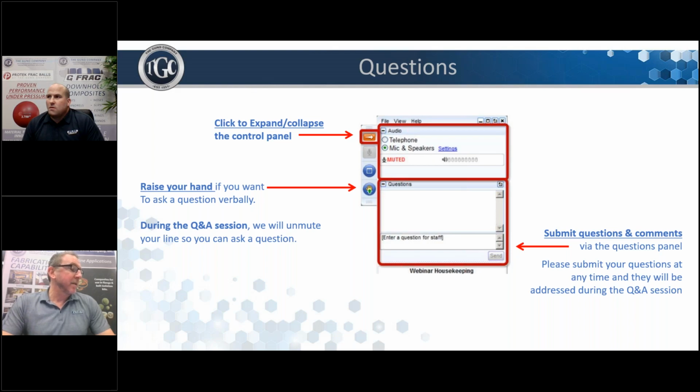But anyway, for the threaded assembly, for sure, yes. Definitely, you can definitely thread G10. It's not a problem. It does pose some challenges if you don't have the right equipment. Depending on the size, you have to have a pretty sizable lathe and the right cutting tools to do that. And for quality, you want to make sure you've got a gauge so that whatever you're threading the G10 onto will mate up properly.